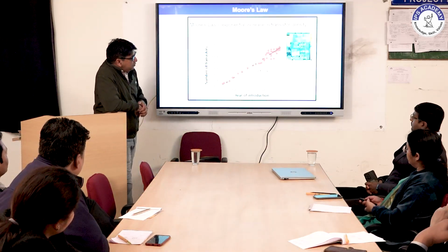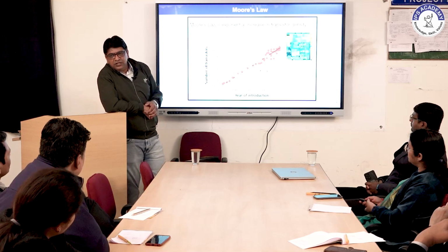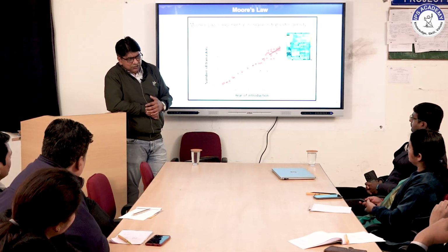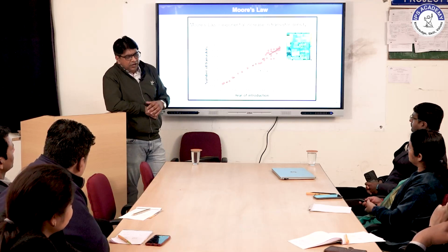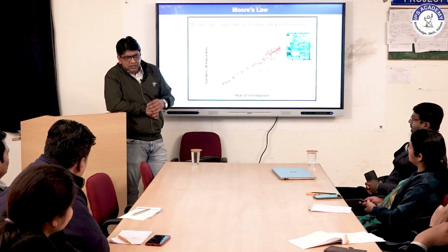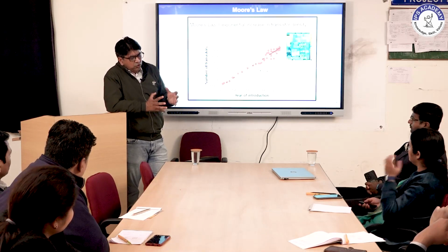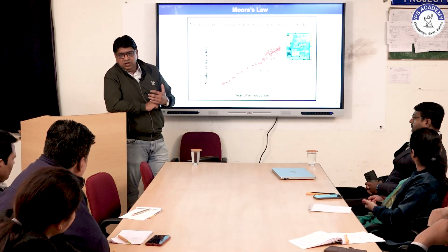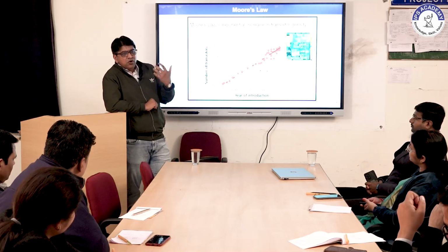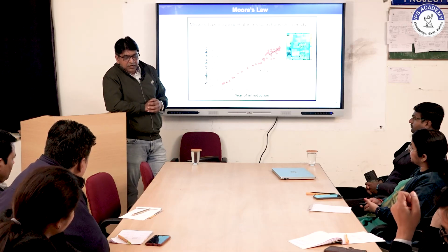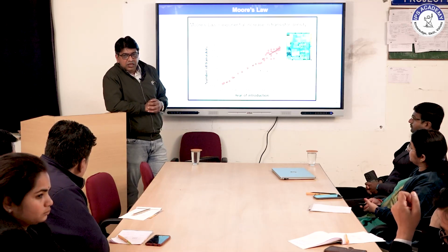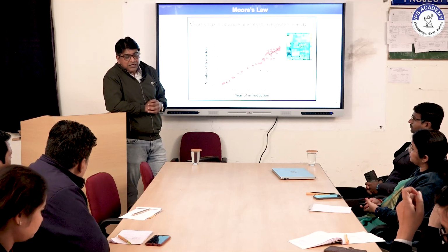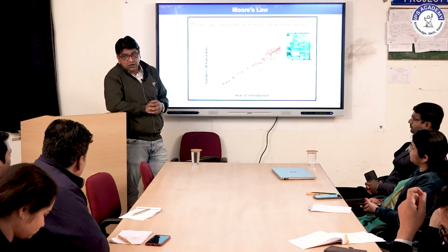You all know about Moore's law. Ultimately, everything is happening towards Moore's law, and researchers are suggesting that Moore's law is going to end. The second thing is that Dennard's density rule is also there. Moore's law tells us to make the chip more powerful, meaning we are placing more and more transistors on the chip. Dennard scaling suggests that if you keep increasing the transistors, you have to scale down the supply voltage also. But the supply voltage we cannot scale down like that.